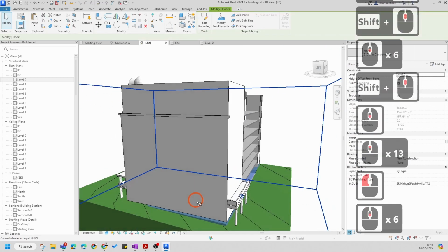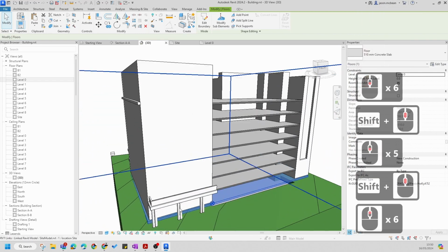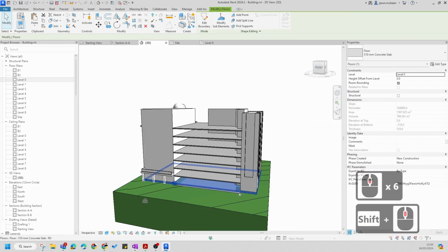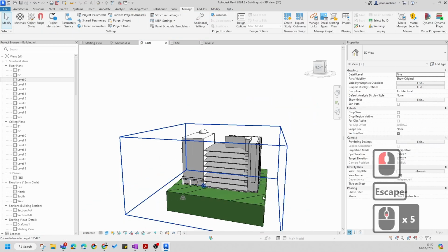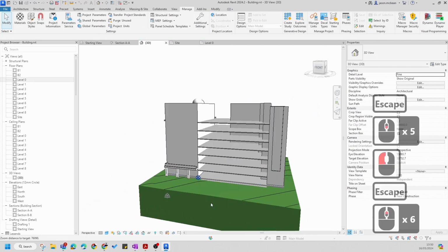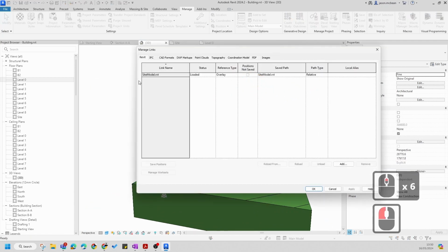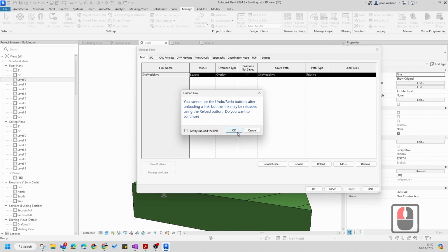Okay. Here you might have to fine tune it to work with your slab, but in essence, once you get the hang of this, you'll start making these adjustments quite easily. You might have to open the site model and increase the size of your basement. But anyway, now that we've got our basement in the right location, what we need to start doing now is adding some walls to the basement. So concrete walls, brick walls, you name it. So here you can switch this off, unload this again because we don't need it.